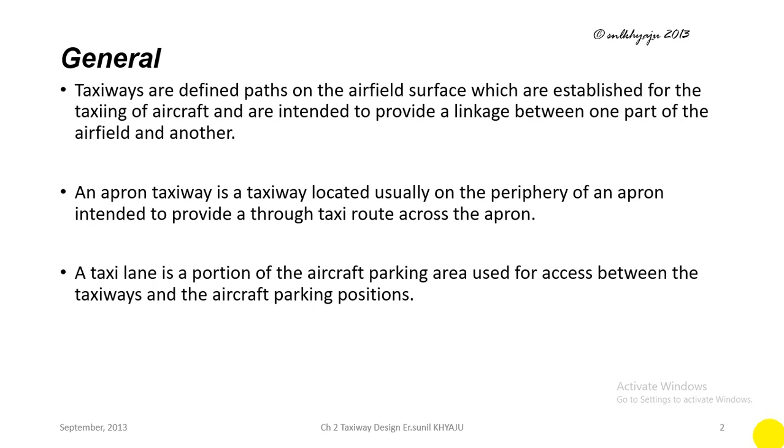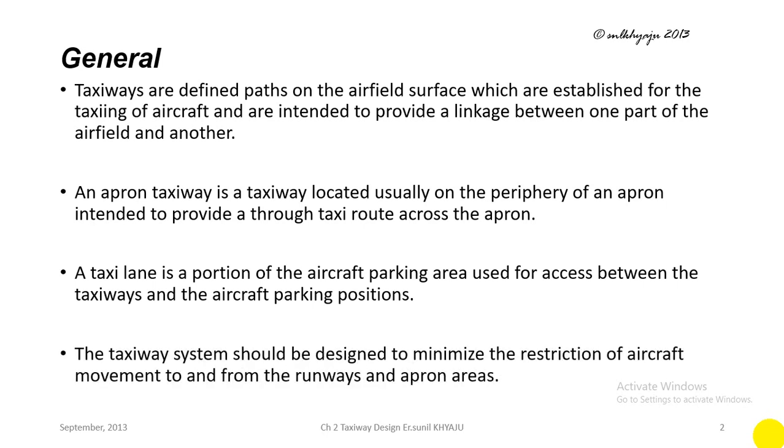A taxi lane is the portion of the aircraft parking area used for access between the taxiways and aircraft parking positions. The taxiway system should be designed to minimize the restriction of aircraft movement to and from the runways and apron areas.